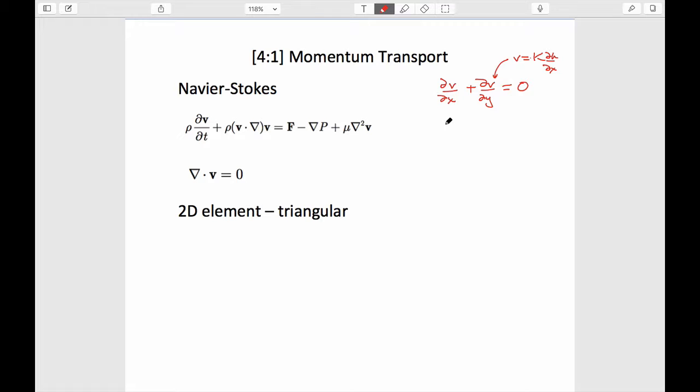And so this is where our second order PDE comes from, which is ultimately kx d2h/dx squared plus ky d2h/dy squared equals 0. And so that's the equation that's typically used for groundwater flow. And you'll note two things. We've all said that when we develop these finite element equations, we rely on maybe three principles.